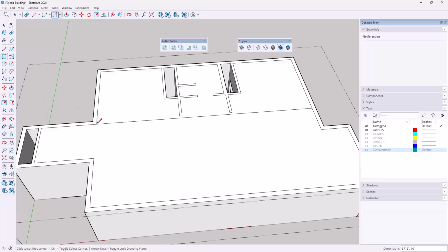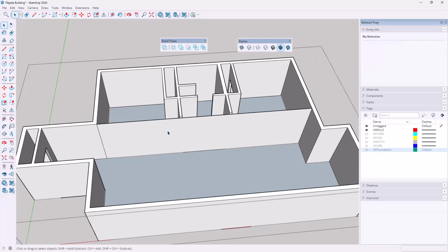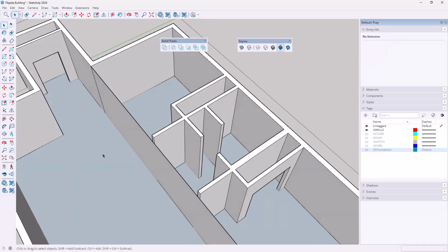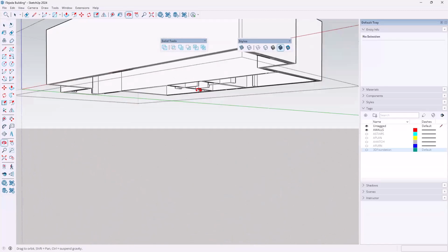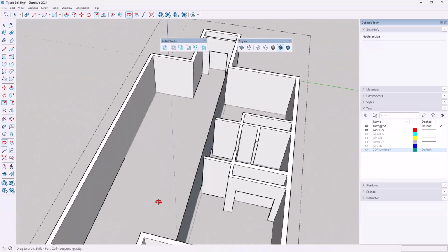And if you have any discrepancies, then try doing it a different way or double check that AutoCAD drawing. So I'm going to click right here. And what it did, interesting here, is that it just assumes that I wanted to close that whole area off, which I don't. So I'll tap the space bar. I will click on this surface, tap the delete key, click on this surface, tap the delete key. And what I'm left with now is this wall here. Oh, and I'm also noticing that it put in a floor or a surface on the floor. So I'm going to take that, tap the delete key, and then click over here and tap the delete key. And just to make sure, I'm going to orbit and okay, nothing on the bottom. Great. And then I'll bring it over to this side.